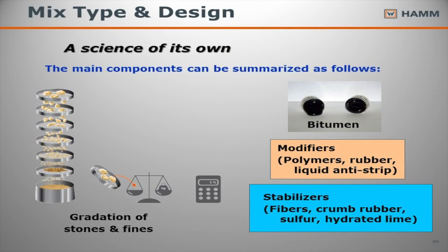So when we look at it, we also have to have the right gradation. We have different types of bitumen asphalt that we look at, different modifiers that we can put in it, whether it be a polymer, a rubberized asphalt, or anti-strip. Different fillers depending on what type of mix it is. If it's an SMA, we're going to have some kind of fibers to reduce the oil drain down so that we don't have puddles out there when we're trying to compact. A lot of different things, and like Trenton said, not every mix is going to compact the same and react the same.